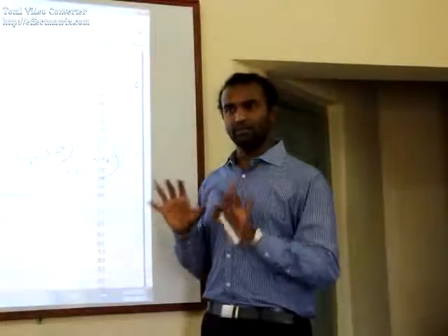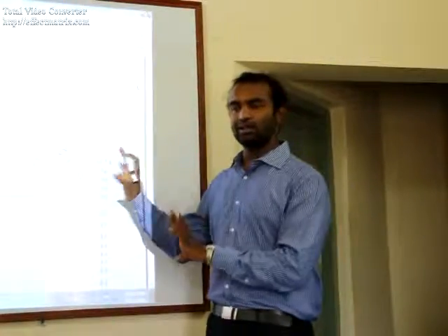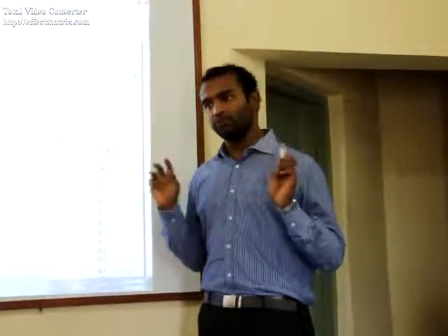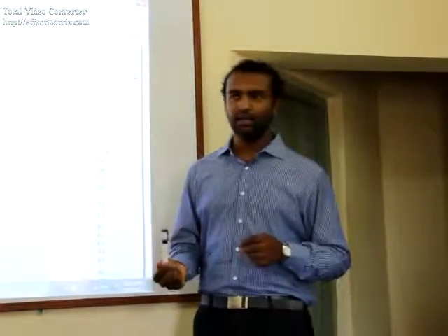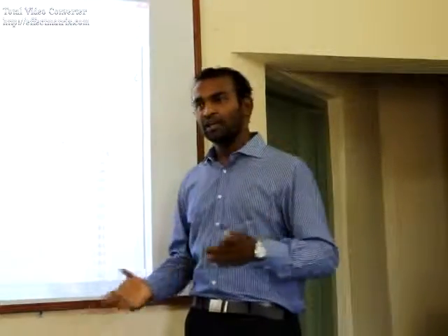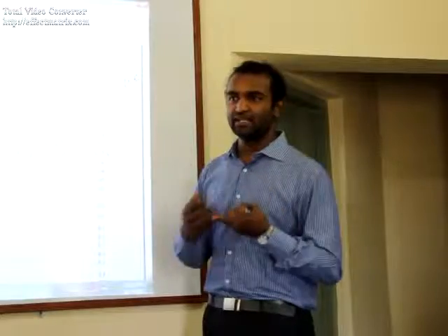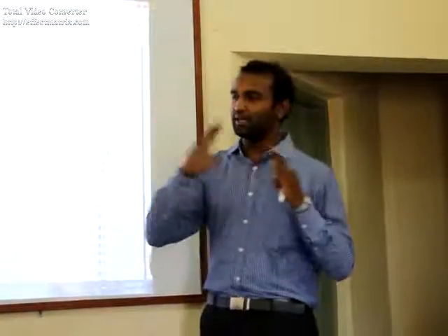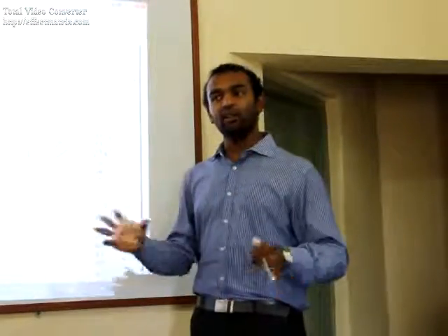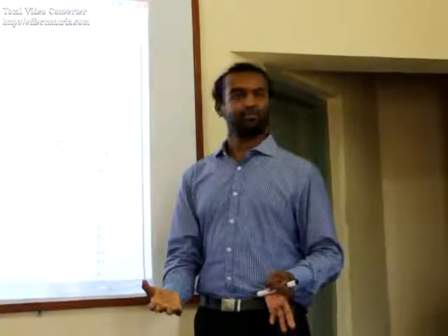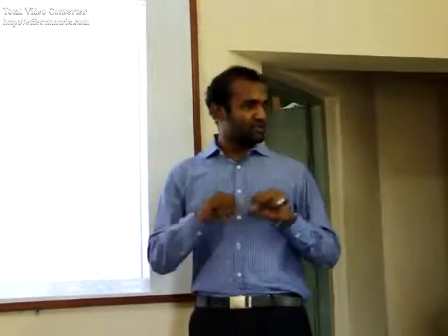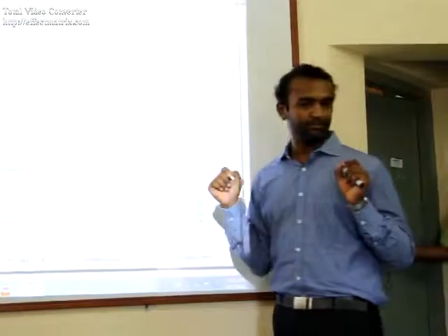I'll show you with images, with videos, I'll show you all this with live code. How does a thermocouple look? Because I'm sure many of you have not even seen what an RTD or a thermocouple is. If I take thermocouple categories, you have many categories, right from J, K, L, M, N. There are many categories of thermocouples, of which various ones are used for various applications. Correct? Next we have stress measurement and strain measurement.